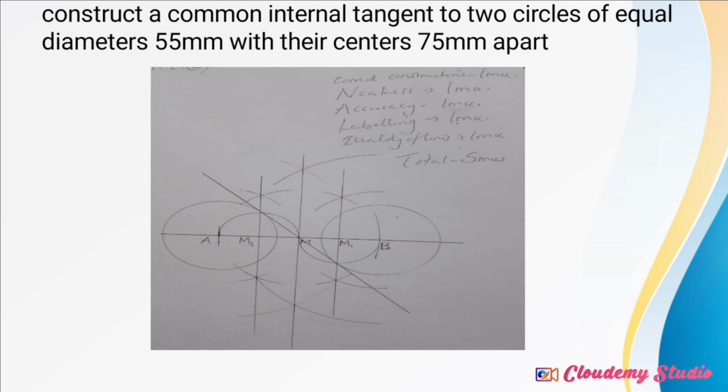To get the second and third midpoints, if you look at my diagram, I've labeled M, M0, M1, M2. So to get the point M1, which is in between the main midpoint M and point B, I also construct by dropping a perpendicular bisector between the 2 points M and B. I stretch my compass to 3/4 of that line, make 2 arcs, one above and below, then stand at point B without changing the radius. I make arcs above and below and I join. It forms the midpoint M1.